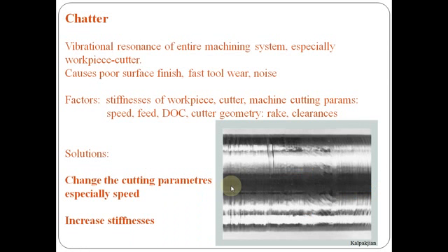So the irregular machining will result in surfaces like this, which may be a result of the vibrational resonance of the entire machine system or the workpiece and cutter alone, which causes a poor surface finish and fast tool wear, and noise may be affected.